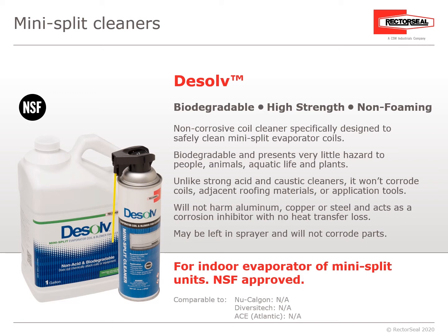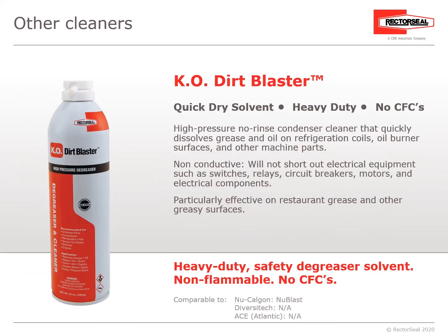It is NSF approved. And under the category of other cleaners, we have KO Dirt Blaster. It is a quick dry solvent, heavy duty, no CFCs, and non-flammable. It's a high-pressure, no-rinse condenser coil cleaner that quickly dissolves the grease and oil on refrigeration coils, oil-burning surfaces, and other machine parts.